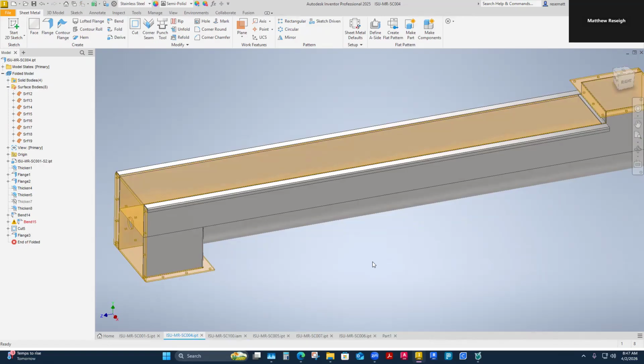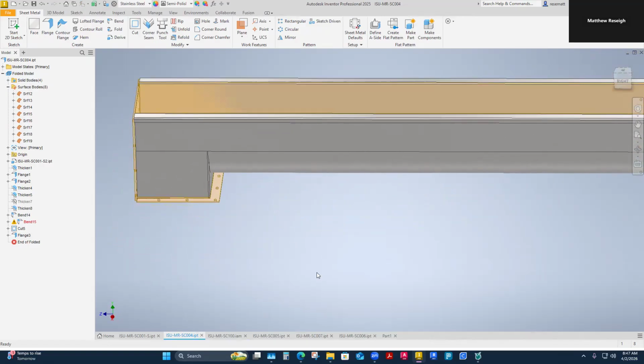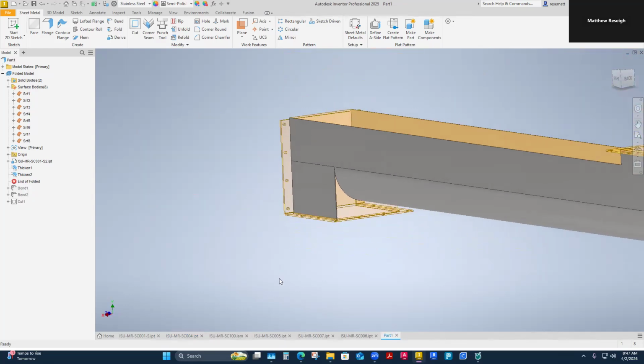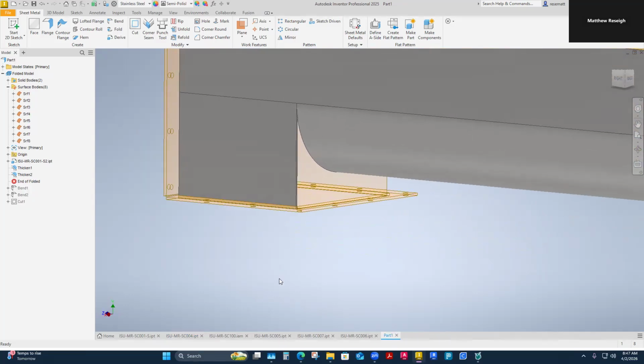Okay, so I'm back into this one. So yeah, this is the one I'm messing with. It was the original first part we created, and we derived the solid. And that's kind of what I've recreated here to show you what I'm doing. And then I've gone back and located the original command that I thickened this discharge chute from, and I've actually stripped away all the faces and only made one face thickened.